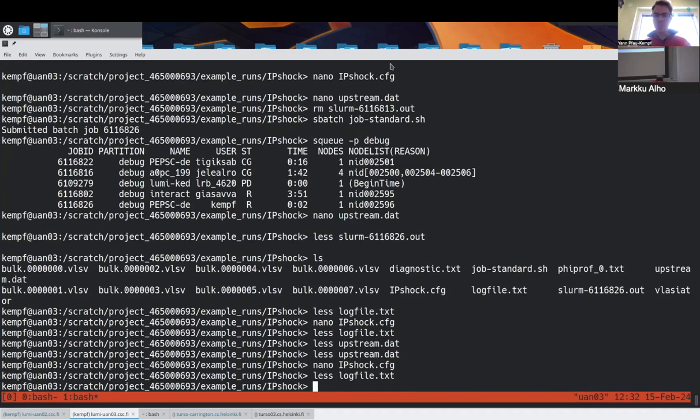So if we're simulating a shock, one can use the algorithm for the active mesh refinement to determine the highest gradient at the shock, and then use... but that's not only at the shock. It will refine the mesh wherever there is something interesting going on. So, I mean, this is open source software. Feel free to start toying around with ideas like this, and if you get something working, we are of course happy to take it into the code base.